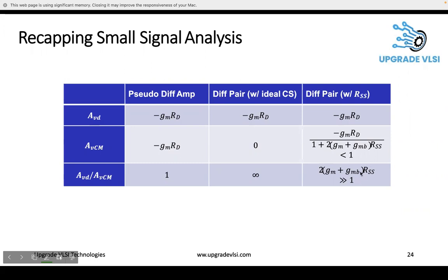The only option to improve the common mode rejection ratio is making a better current source. The tail current source needs to be better, in the sense that its output resistance should be much higher. GM basically depends on many other factors, so we need to look at the GM and size the diff pairs accordingly.